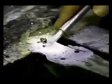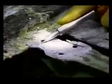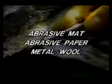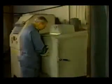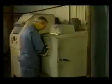The primary methods of corrosion removal used in the field are mechanical. Mechanical corrosion removal is done either by hand or with handheld power tools. Hand sanding uses abrasive mat, abrasive paper, or metal wool and is suitable for small areas. Powered mechanical sanding, grinding, and buffing use abrasive mats, grinding wheels, sanding discs, or abrasive rubber mats. Abrasive blasting is the most thorough method for removing rust from both low alloy steel and high-stress steel surfaces on the aircraft exterior.